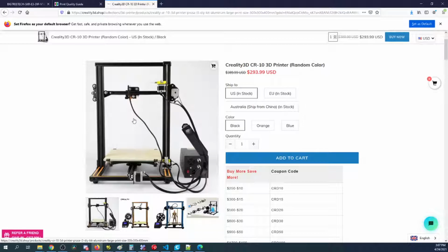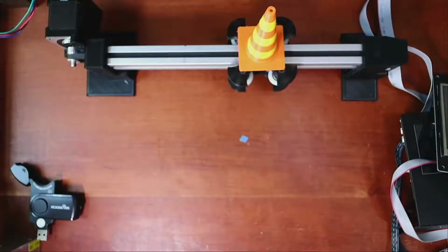So the issues that you're seeing, what's the heat that you're using when you actually print? What temperature are you extruding at? And what material are you using, and has the material been exposed to a lot of environment or not?